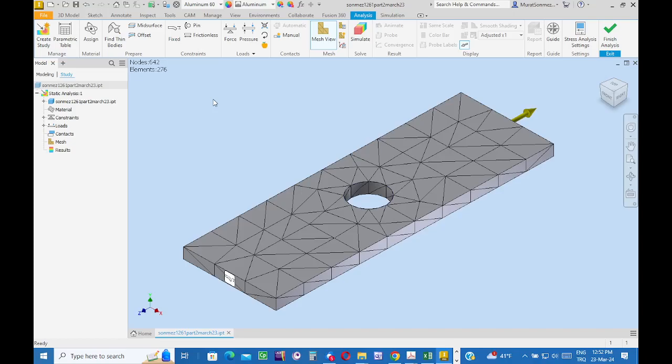the maximum stress values, and the places where, if I say 70% of maximum stress, at the end of the first run the program will say that this is the maximum stress, and at the other points the stress is 75% of the maximum or greater than 75%. At such places, Inventor decreases the mesh size. It's going to be automatic.